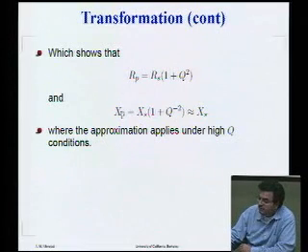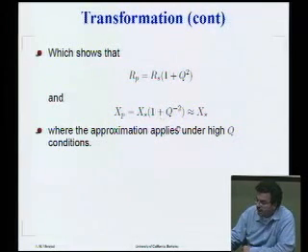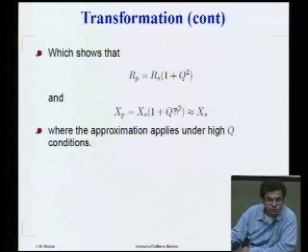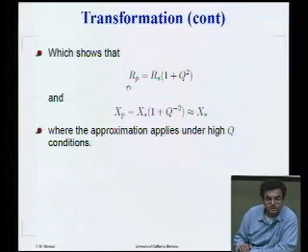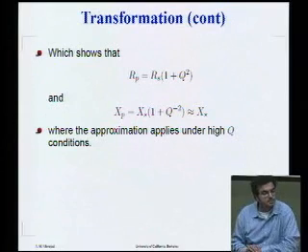And likewise, you'll find that the parallel reactance is equal to the series reactance times 1 plus Q to the minus 2 power. Okay? And this is also a nice result because usually I have high Q circuits. So for high Q circuits, 1 over Q squared is small, so I can see that the reactance actually doesn't change much. Whereas the resistance, this small series resistance, turns into a large parallel resistance, and vice versa. Okay? Any questions about this transformation?